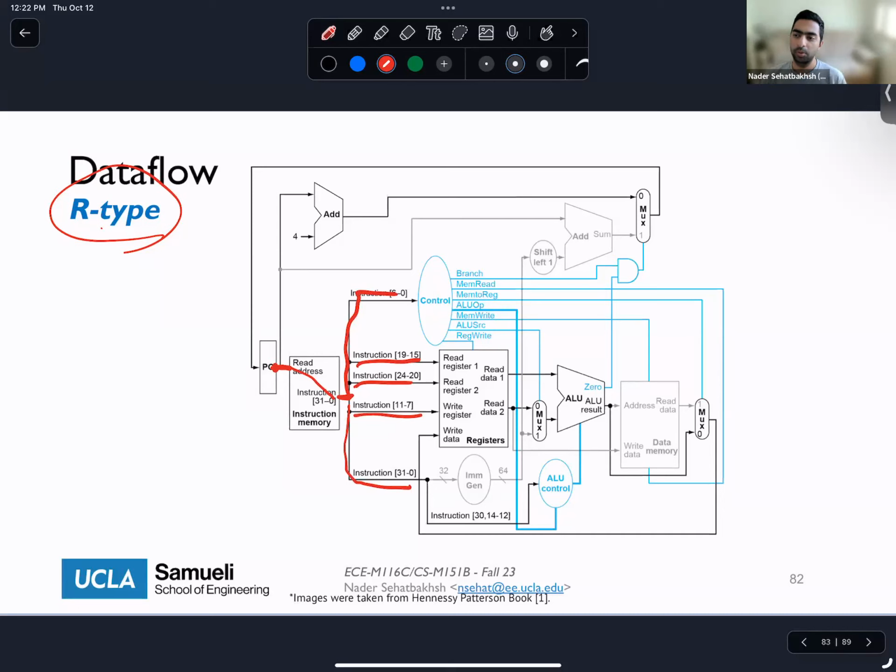One thing that I've noticed people have difficulty with is that in hardware, things are synchronous and parallel. In software, when we are writing things, we write one function and another function, and the functions don't happen simultaneously, right? So we always have this sequential execution of things. In hardware, that's not the case. Our controller, our register file, our immediate generator, for example, all at the same time take the same thing. And more importantly, for example, once the PC gets updated and goes through the instruction, also this value gets updated, okay?